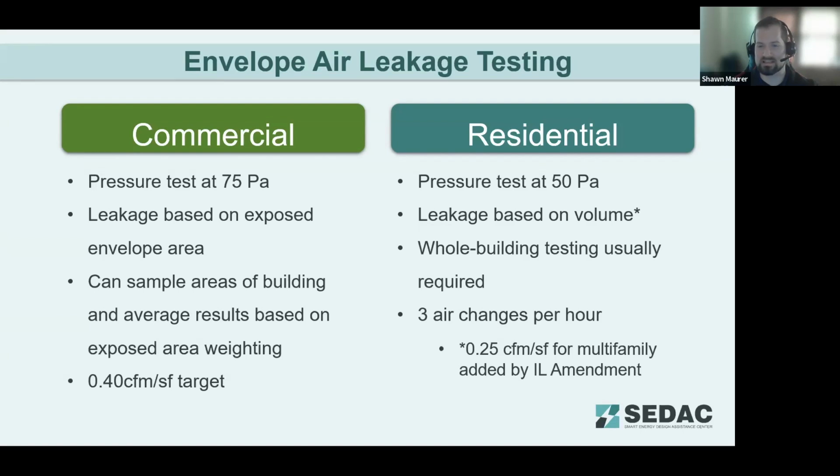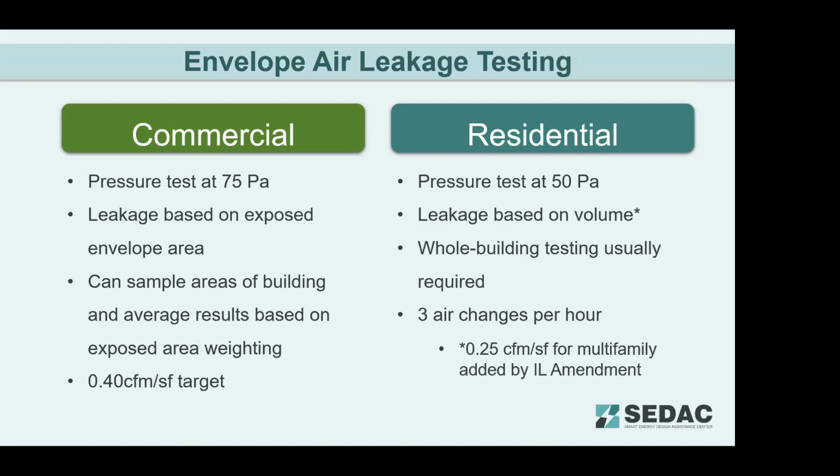But why are we doing this test? We want to ensure that that envelope is sealed, so that you're limiting air changes in the building that are uncontrolled. We want to make sure that that envelope isn't going to have issues with humidity entering, that you can have condensation damage, things like that. So that's why this test is important to do. And Todd will touch on later the actual methods of sealing up the building for the test, what should be sealed, what shouldn't, as far as sealing up air vents and things like that in the building.